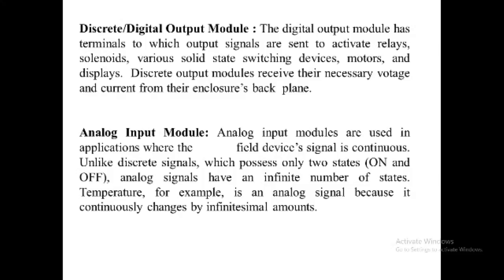This condition will remain on as long as the output table corresponding image bit remains equal to 1. When the signal turns off, the 1 that was latched in the logic section is unlatched and the off signal passes through the isolation circuit, which provides no voltage to the power section, thus de-energizing the output devices.